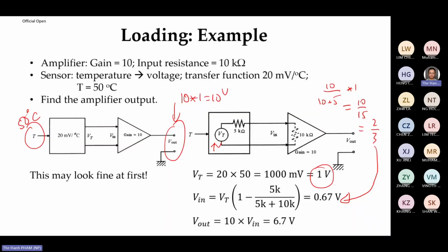Okay, so that's why you learn quite a lot of op-amp circuits, right? Because one characteristic of the op-amp is that the input impedance is very high, right? So you can use the op-amp to build interfacing between multiple subsystems.